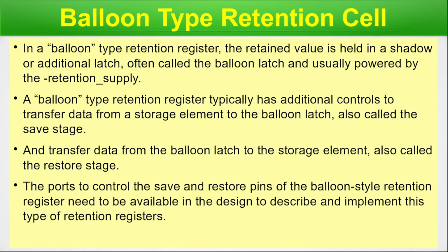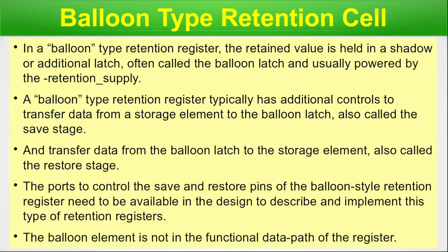The ports to control the save and restore pins of the balloon style retention register need to be available in the design to describe and implement this type of retention register. The balloon element is not in the functional data path of the register. That was all about the balloon type retention cell, and we are done with this particular slide. So let's move on.